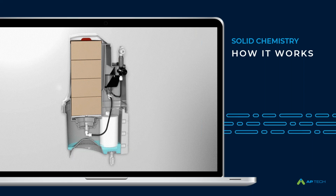It collects in this reservoir, and then you use a chemical feed pump to extract the material out. You'll always have solution in this unit as long as you have positive pressure to the control valve. It's self-regulating, it's instantaneous. You can confirm solution strengths by pulling samples and running conductivity testing.